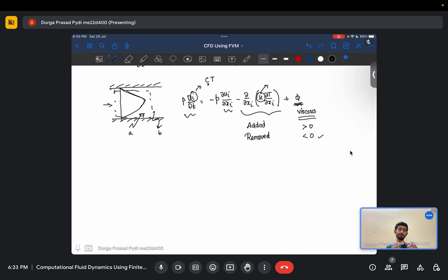So if I tell you that I have an isothermal plate, depending on your boundary conditions, say both the top and bottom plates are isothermal, or maybe I'll just put an adiabatic condition. Isothermal is difficult. Adiabatic you can easily understand. If both the top and bottom plates are adiabatic, then no energy can be transferred to the plate. So the only option left is that the dissipated energy should be absorbed by the fluid. If you have an isothermal case, there are solutions for that. You can Google later. You will find solutions for the isothermal case as well, showing how the flow develops and how your temperature profiles will be.